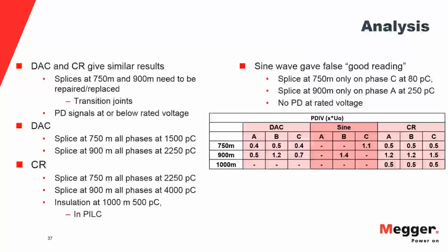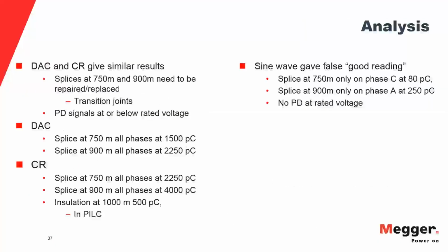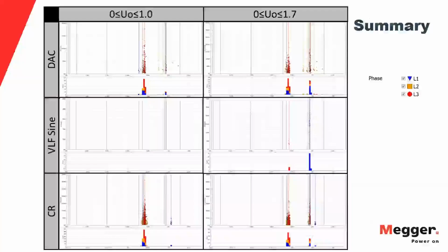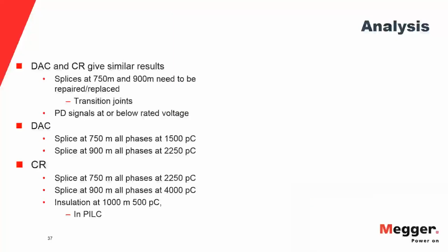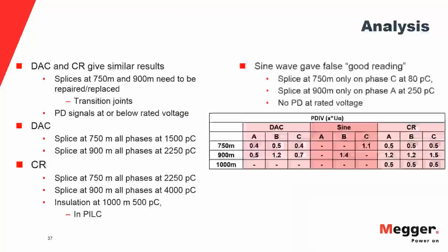And the square wave and specifically the triangular wave are not really common. There's no equipment really commercially available, and it's not supported by standards. So it's sine or cosine rectangular, and then keep in mind in what world you're operating, IEEE and IEC, and there's different test values in those two worlds, and just apply the voltages accordingly.